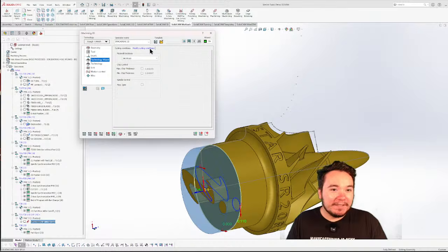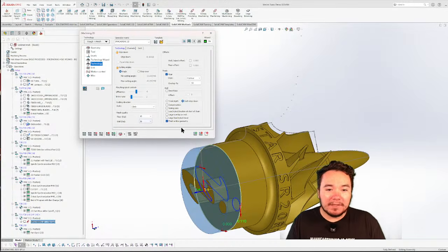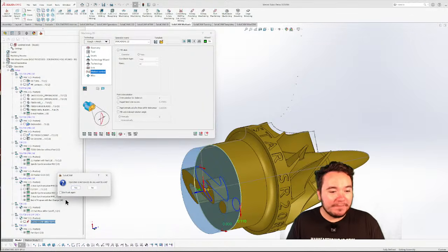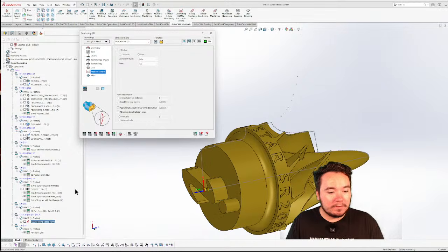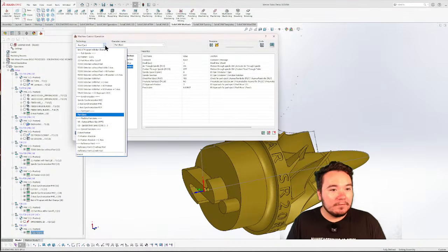It's pretty impressive. Cutting parameters, I didn't mess with anything there. I did do finish entire geometry, give it a Ra finish of 16. I pretty much left everything pretty basic here. So just your normal iMachining 2D operation. Exit. Okay, and then at the end, just added another MCO. Part eject. Simple as that.